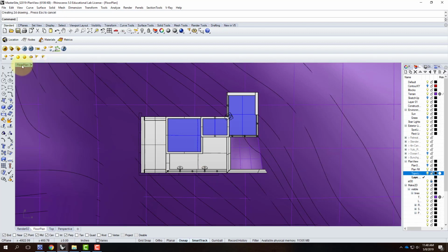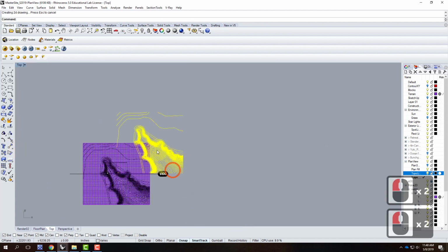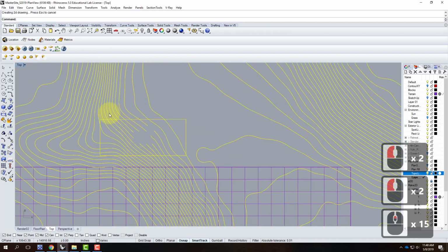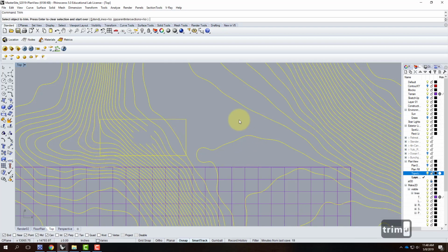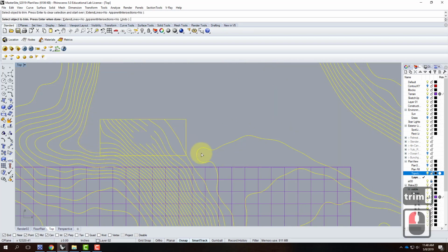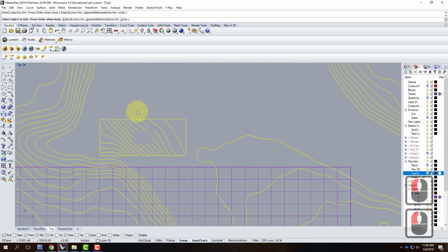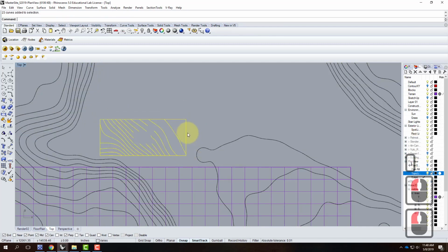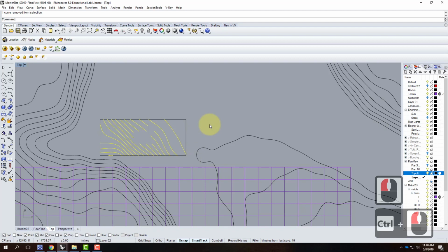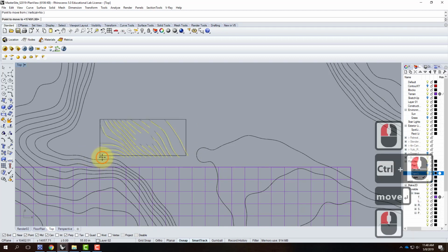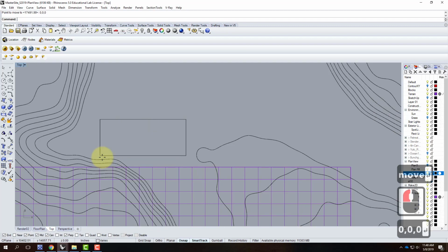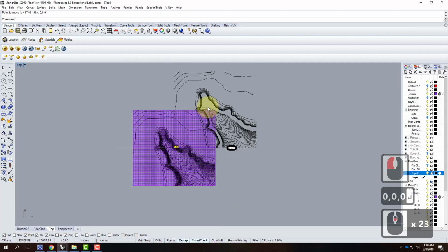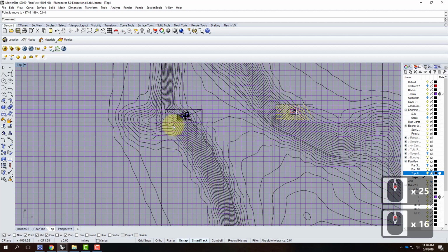There it is. I'm going to look at it in the top view. And there is my viewport boundary and all the extra pieces that I don't need. I'll type in trim, and I'll get rid of the parts that I don't need. Like that. Once I'm done, I'll press enter. And then I can take this, minus the boundary, because I don't need that. I already have it. And I can move that to 0, 0, 0, which is going to give me all those line drawings that I need.